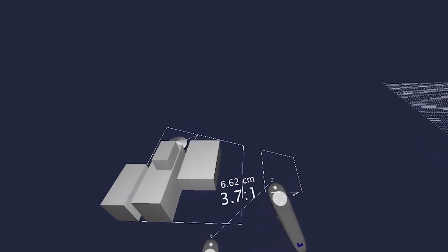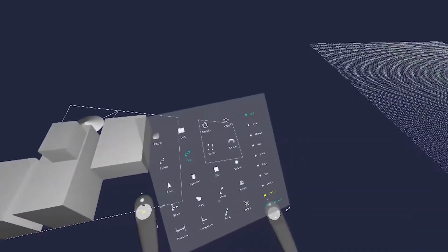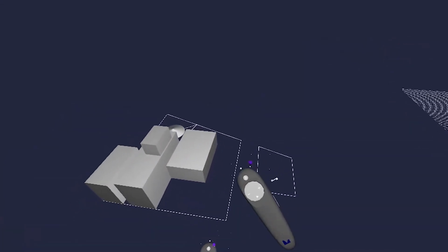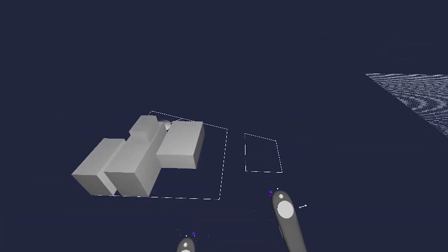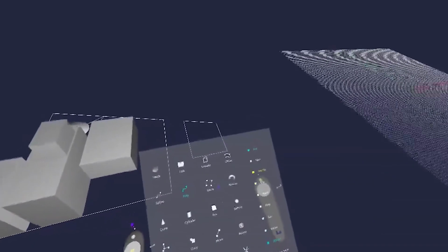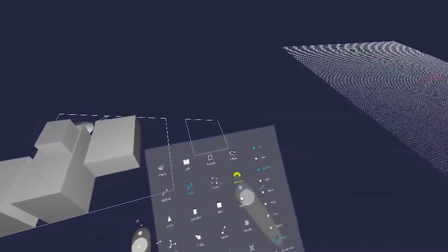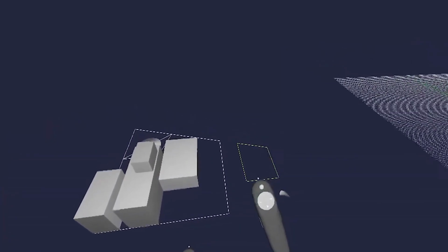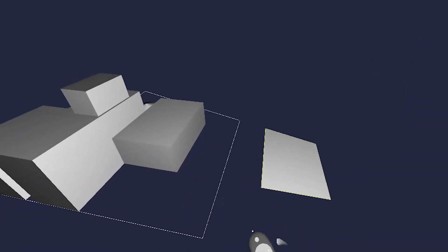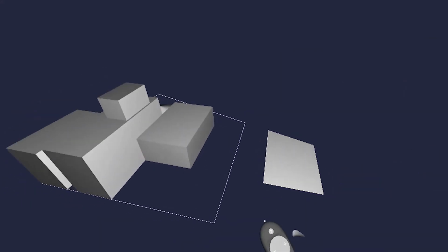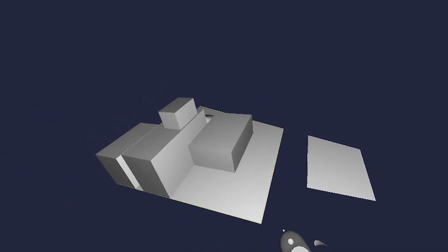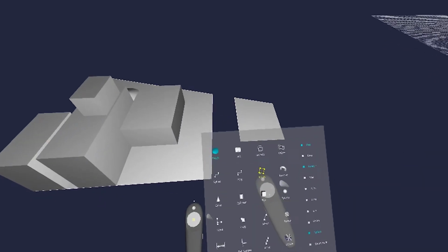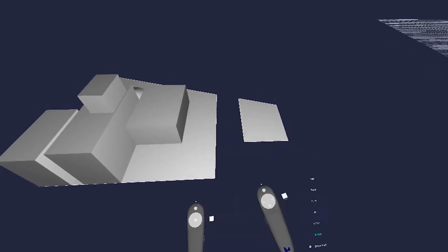The last feature of the precision tools is the 3D grid. This is similar to Grid Snap in Rhino, except in 3 dimensions. This also is only available in Mindesk and not in Rhino. So to show off those 2 unique commands, I'm going ahead and patch this little block to make a flat surface, as well as the larger block, and create 2 more buildings on each site using the 3D grid as a guide, making sure my near surface snap is on.